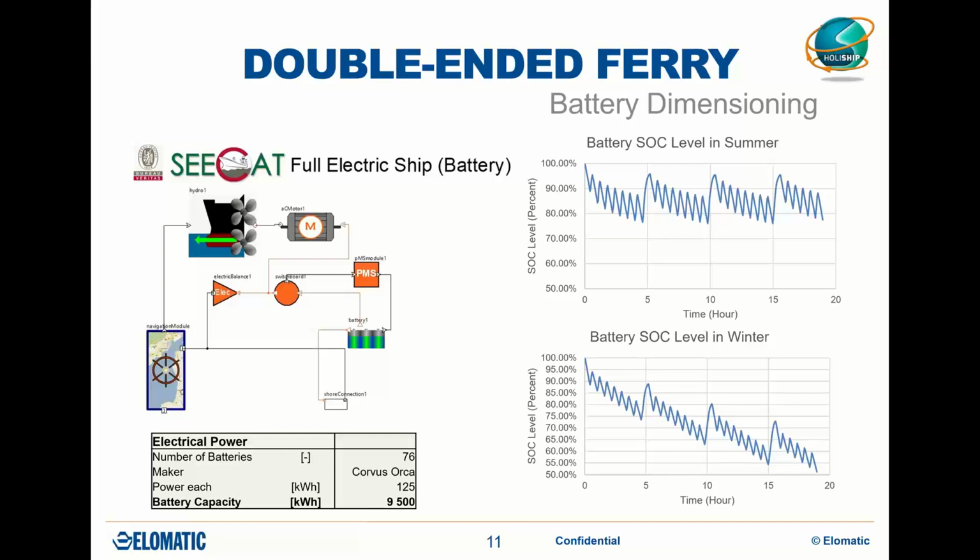Because the battery is a relatively new energy source, we wanted to analyze its performance against traditional diesel generator set options, and this simulation and analysis was done by Bureau Veritas using their energy simulation tool. We dimensioned the batteries based on the ship's operational profile and the state of charge in the batteries.